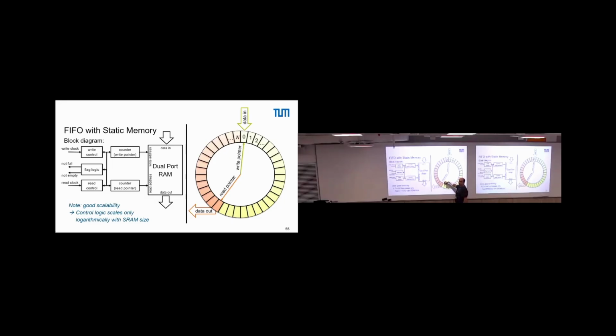To avoid doing this by mistake, there's a write control involved that effectively blocks writing. On the other side, we have the read pointer. If this read pointer reaches the point we have just written, then if we try to read the next word, it's empty, or it's some data from a previous write that is not valid anymore. So we need to say, okay, we are now empty, and we trigger here that we effectively block further reads. Okay, that's not very difficult, right?